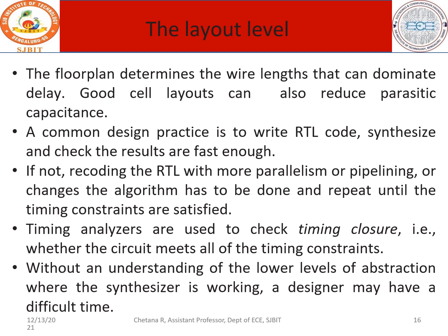So how do we do this? A common design practice is to write RTL code, synthesize and check the results. This has to undergo experimentation, and therefore you have to do it at the register transfer level. You write the entire design in RTL, synthesize the circuit and run it, and that will help you find out whether the layout has good propagation speed or there is a delay, and then you can change whatever you are supposed to change.